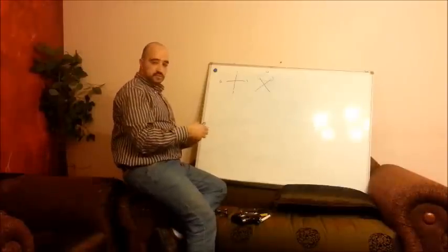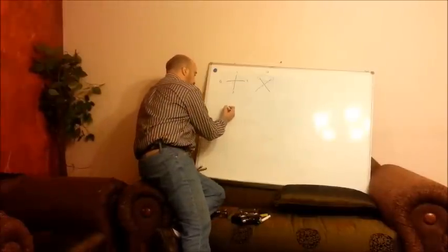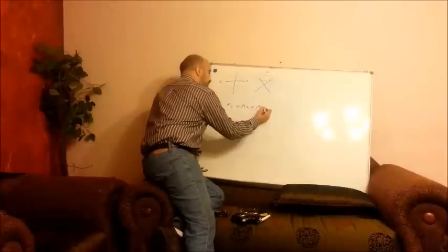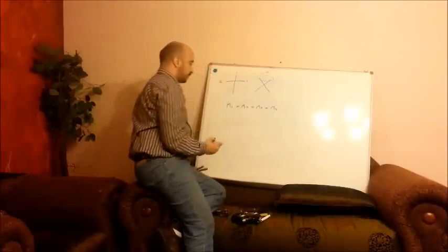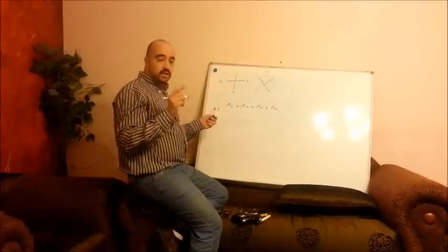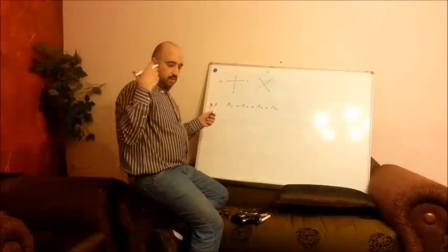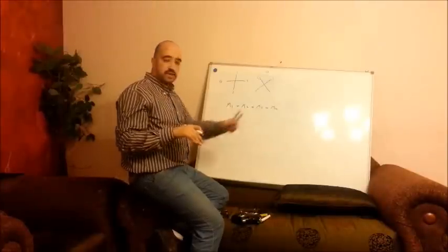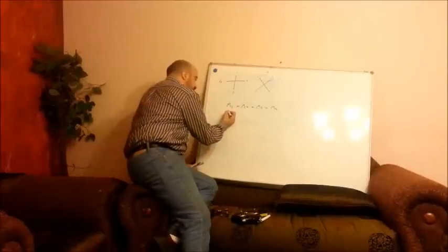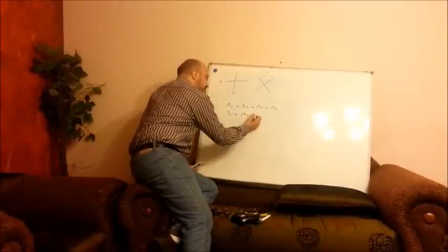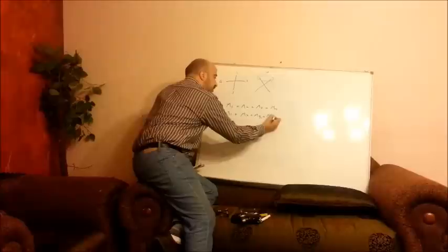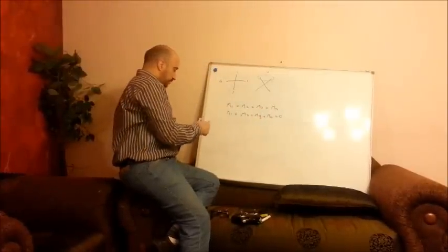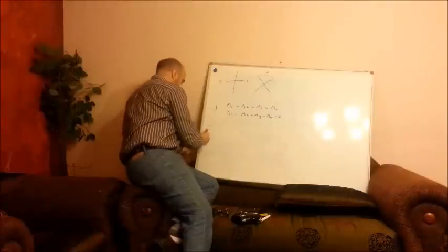The RPM is determined by the thrust. So M1 equals M2 equals M3 equals M4 is valid if we ignore the effect of the balancing algorithm. And M1 plus M2 plus M3 plus M4 equals a constant that is determined by the thrust. This is the first rule.